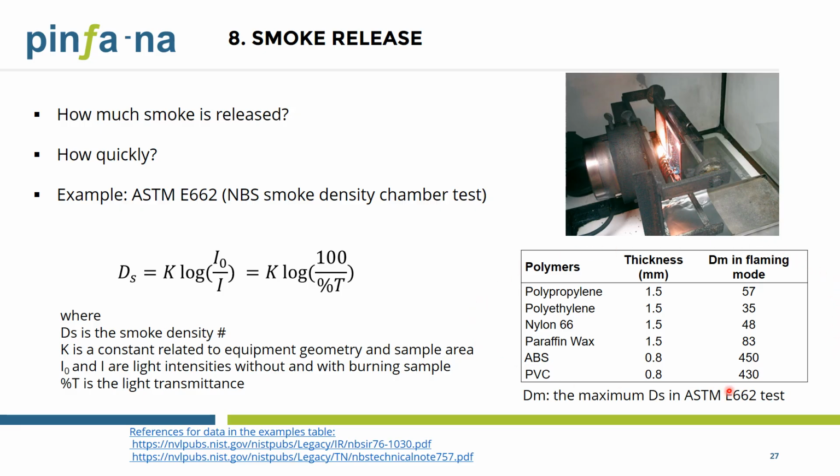It should be noted that smoke formation is not an inherent property of a material because many other factors such as sample size, sample orientation, ventilation, and heat flux can all affect the amount of smoke generated in the test. But the structure of a polymer does influence the smoke formation tendency of the material. A couple of very simplified generalizations could be made as follows, but there are also exceptions.